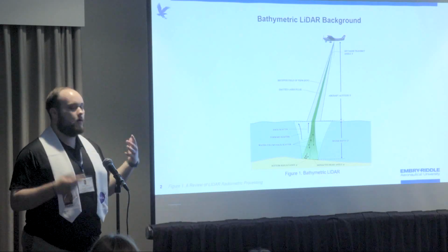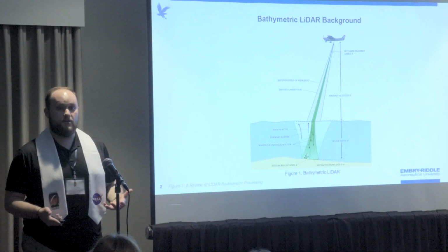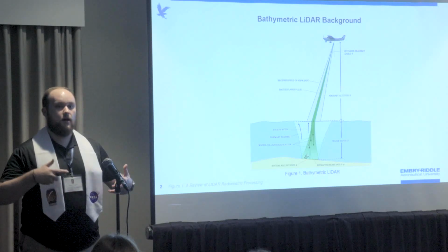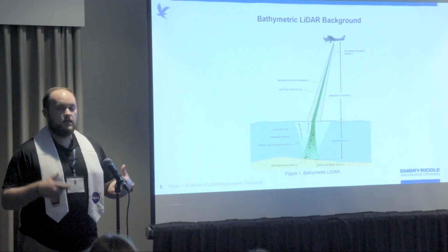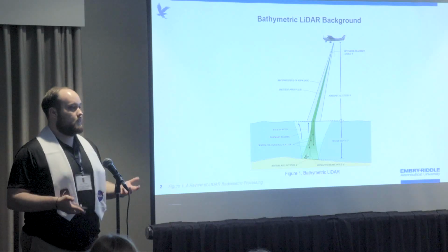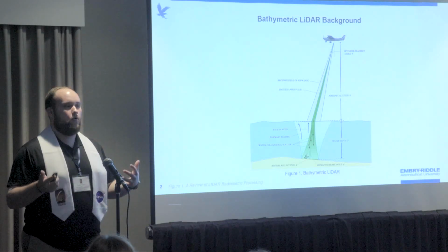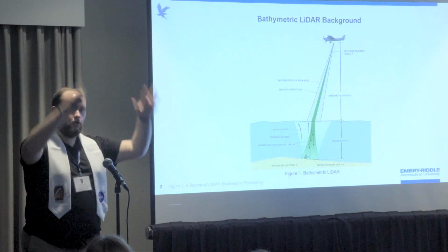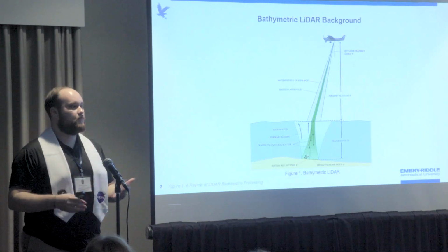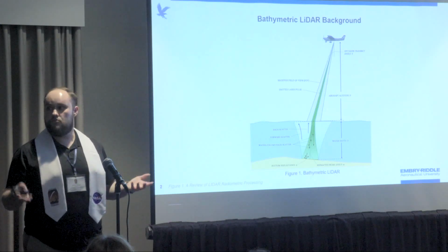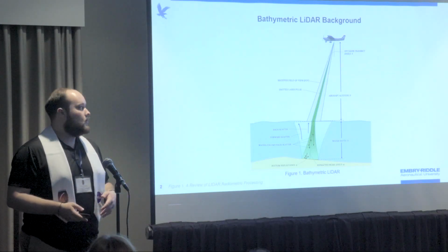A big issue with bathymetric LiDAR is the turbidity of that water, specifically suspended particles. These suspended particles can result from many different things, including just natural currents in the water, or someone throwing a rock and particles start suspending. And this can be as basic as dirt and sand, or even more complex with living organisms.